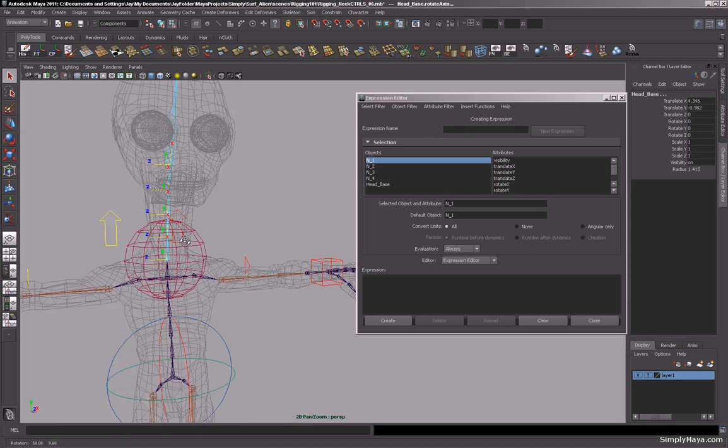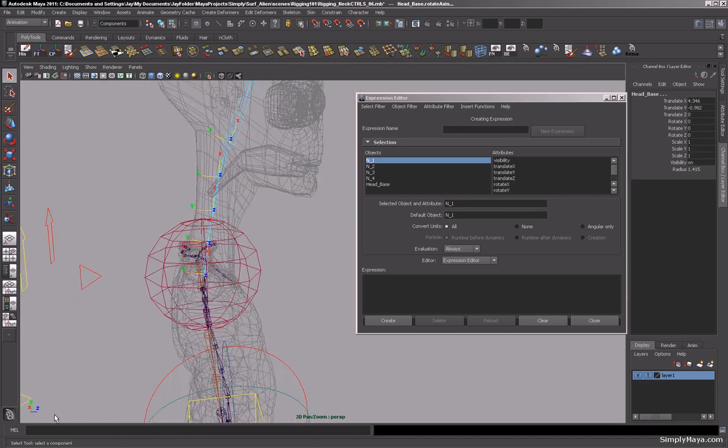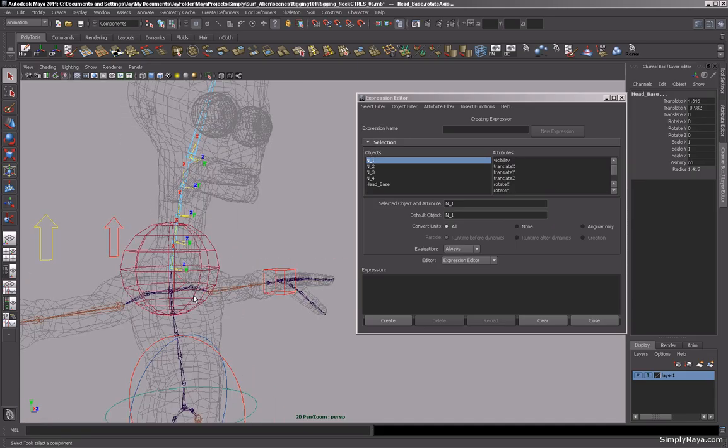And what we need to do is put in a simple rotational MEL script, and we'll just pop that in down here on the MEL command line, and that's going to be rotate -r -os 180 0 0, then semicolon, and the 180 is going to be the actual axis around the X. We're going to be rotating the axis 180 degrees around X, and Y and Z will be left at 0. So once that's done, hit enter, and your axis should flip towards the front, making them the same as the back.